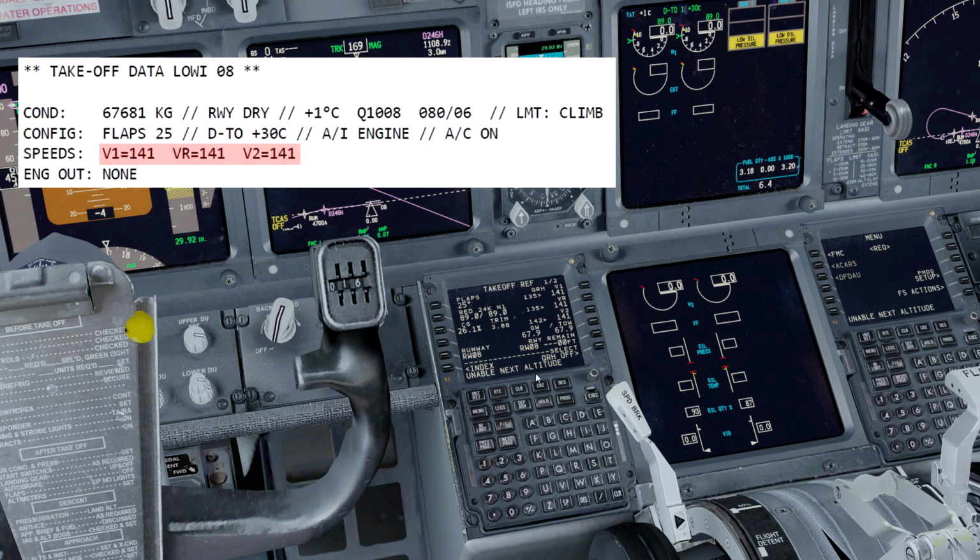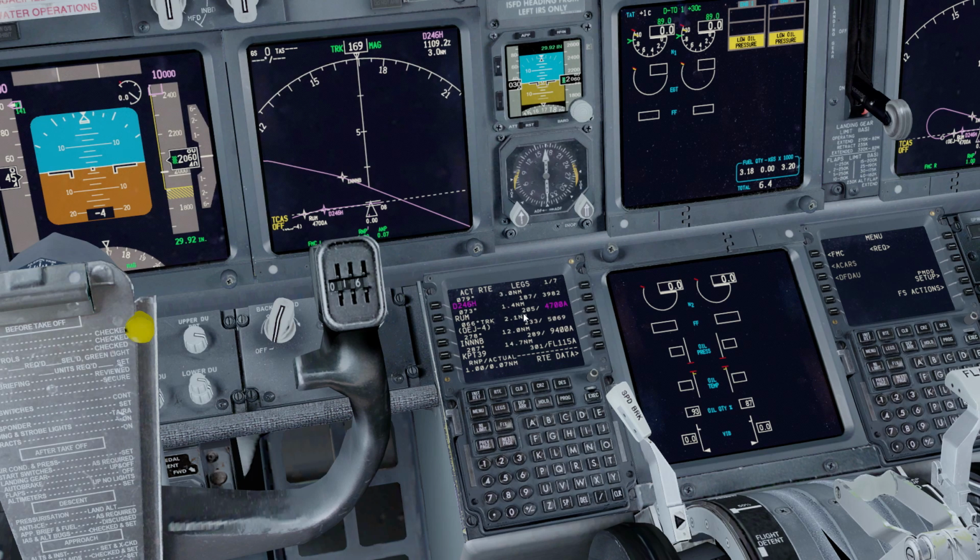If there are any warnings, you just have to make sure that you check with the flight plan whether you are able to meet all the restrictions across the flight plan. Okay, so make sure, for example, during the SID you're crossing this waypoint Romeo Uniform Mike above 4,700. If you're not able to, you might want to advise ATC.